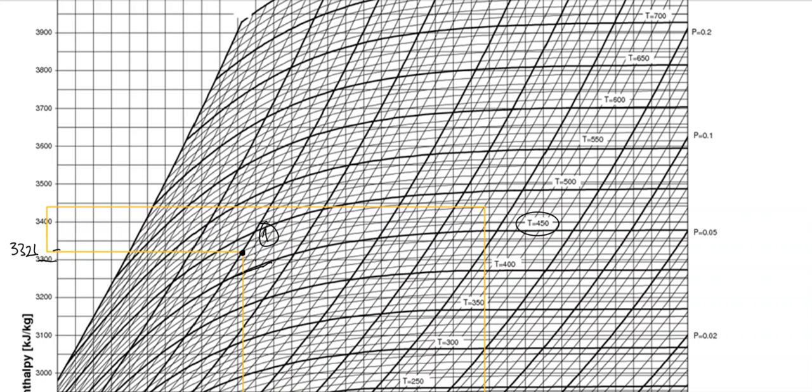We will check it later on with the steam table anyway. So not precisely, but I would say the enthalpy at this point, 10 megapascal and 480 degrees centigrade, is 3324.